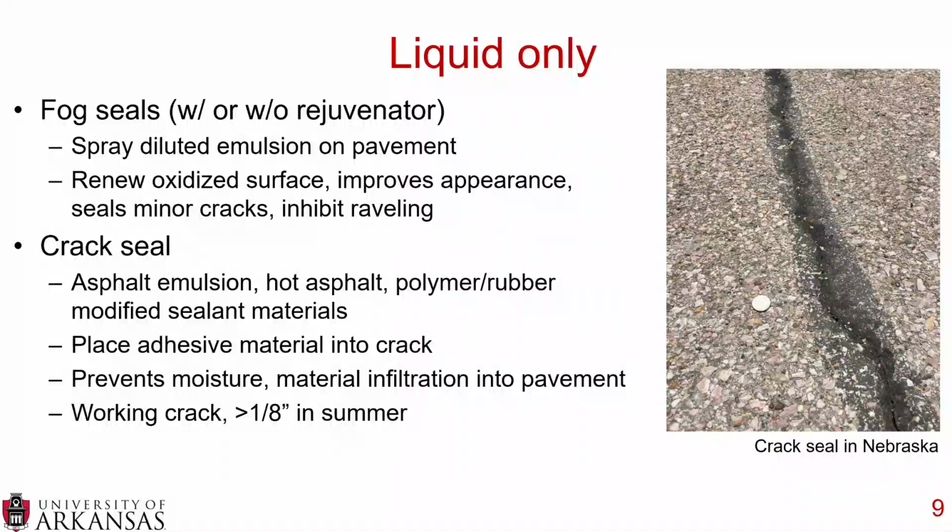And you crack seal when you have a working crack. That means it's moving in and out, and it's greater than 1/8 of an inch during the summer. And that's important because that is compared to a crack fill, which is non-working, and it's less than 1/8 of an inch in the summer. So there is a little bit of a difference there between crack seals and crack fills.